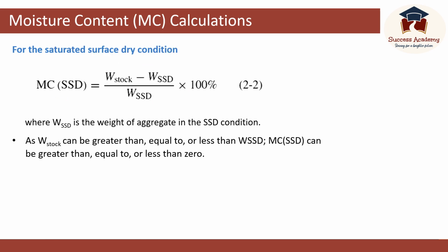Moisture content for surface saturated dry condition is also calculated in the same way, but here instead of using the oven dried weight of aggregates, we are using the surface saturated dry weight of aggregates.